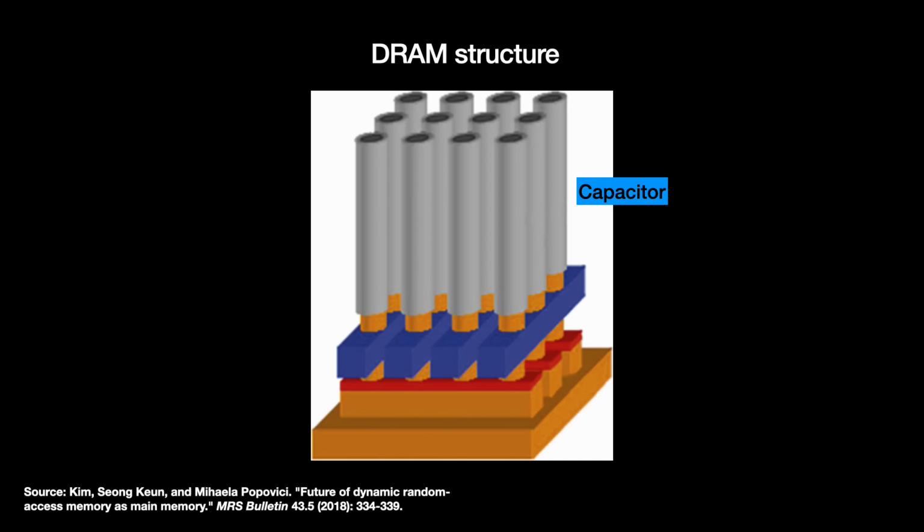If we want to increase bit density, then we have to stuff more DRAM cells onto the same piece of silicon, which means scaling down the DRAM cell's size. But making a smaller capacitor means less capacitance, which has trade-offs. Lower capacitance makes it harder to sense how the charge changes the voltage on the bit line after it comes out of the DRAM cell's capacitor. It also shortens the amount of time the capacitor can hold on to the charge, so we must refresh the DRAM cells faster and more frequently. This is a power suck.